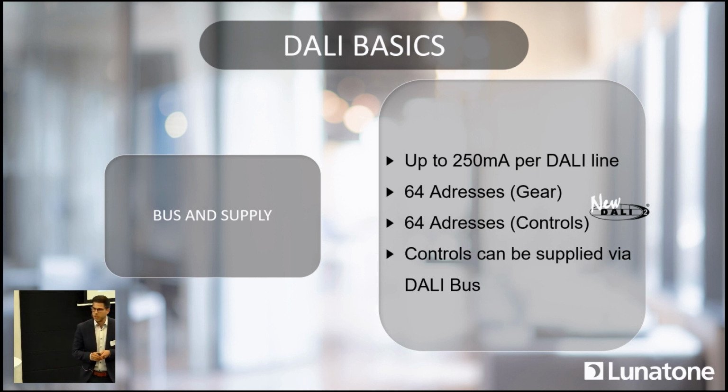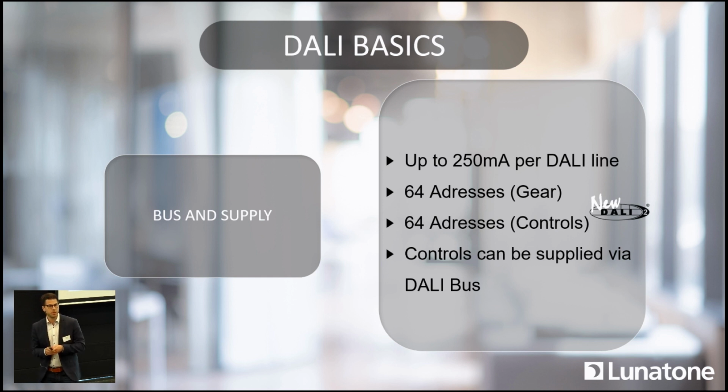But bus power supply can be up to 250 milliamps. So that's kind of a DALI regulation. Now you would think, why do they do it? Why not unlimited? Of course, you have to design the devices to be compatible on every installation, so you need kind of a standard. 250 milliamps is the standard per DALI line.